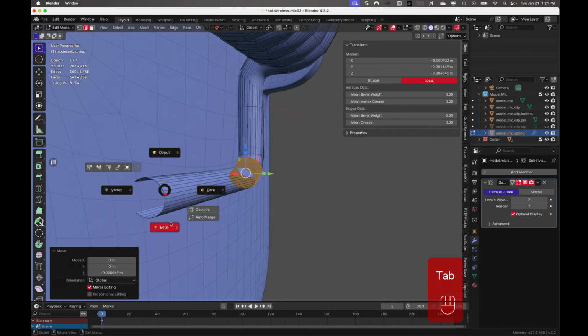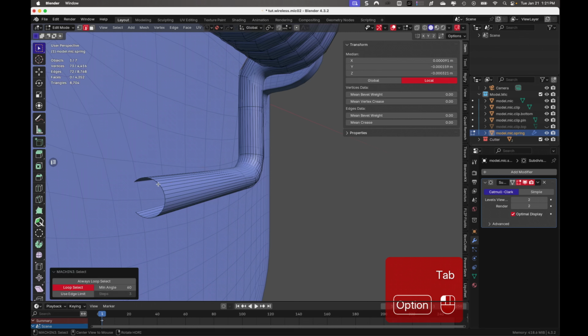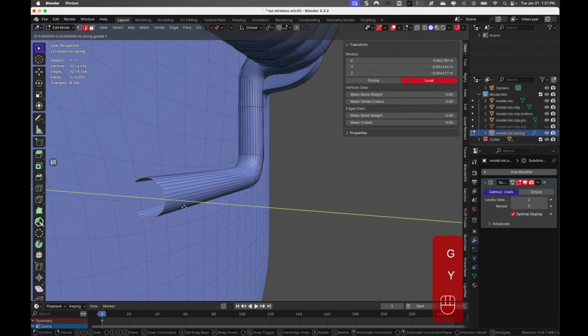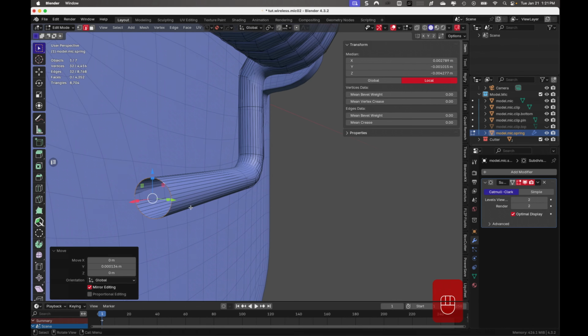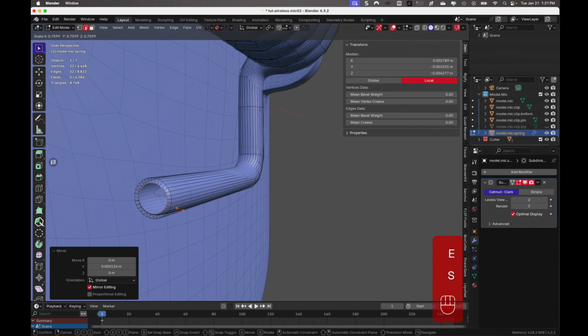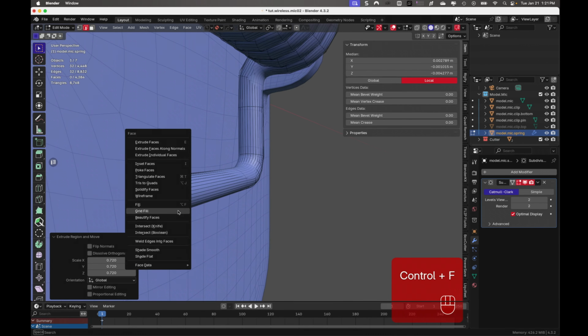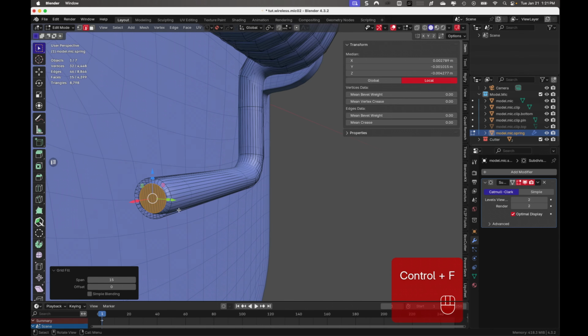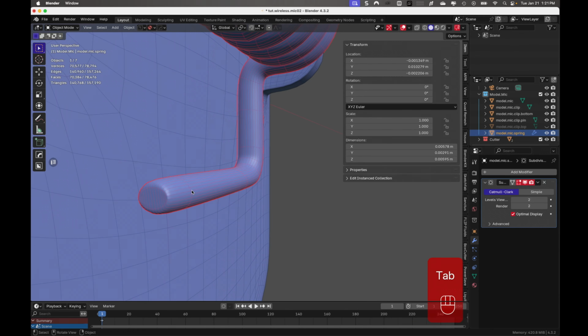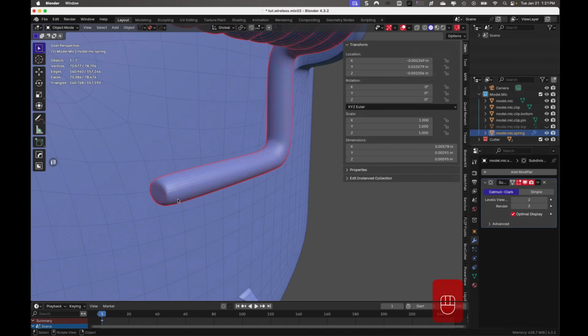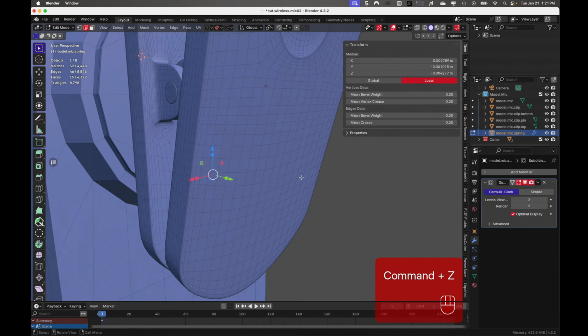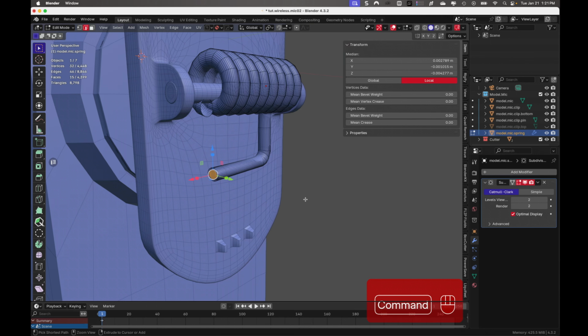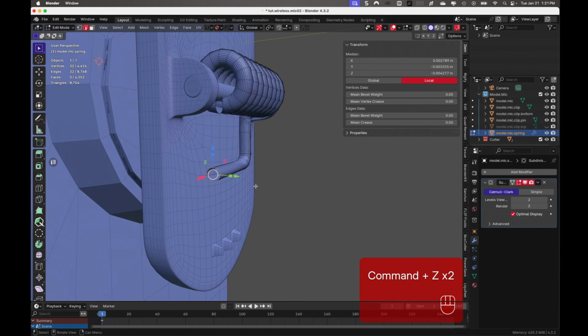And if you notice, the geometry is eating into the clip, so let's grab some edge loops here and gently move it off. Yeah, and that doesn't look real pretty. The reason why it doesn't is because of sub D. But I'm just going to come back in here and do this properly.